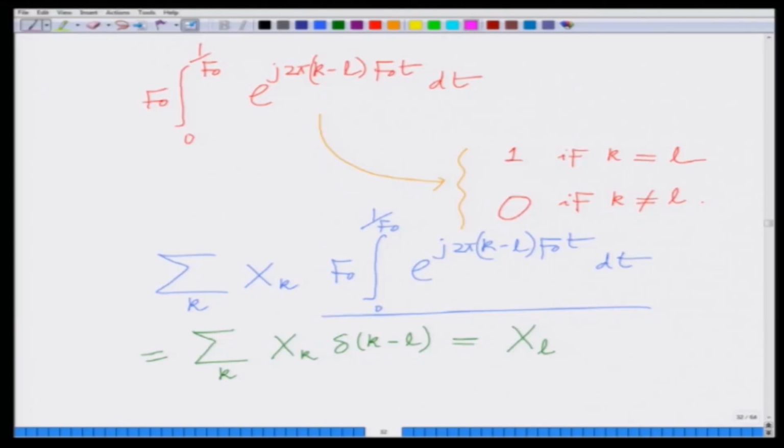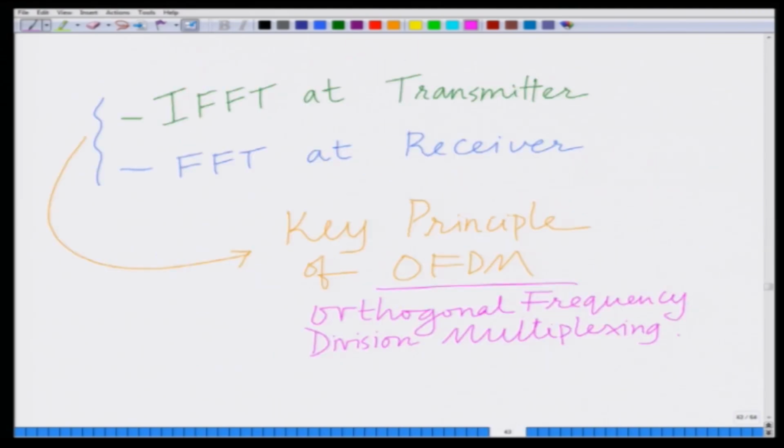The second aspect of this OFDM system is, if you look at this, it is frequency division, right. We are dividing this broadband bandwidth B amongst the n subcarriers, with each band having bandwidth B by n. So, this is a frequency division based scheme, multiplexing, which means we are multiplexing multiple symbols over these multiple subcarriers over the bandwidth B. As we have already seen, we are transmitting n symbols in parallel over the n subcarriers.